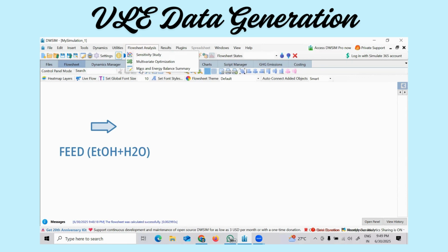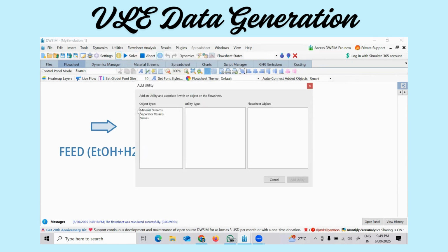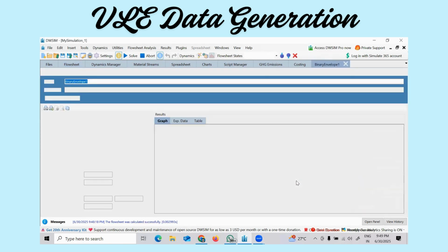Utilities, and then I say add utility, and then material streams. I take binary phase envelope and with stream, and then you can see again, it's all enabled now. Blue colored one, object type is what? Material streams, and utility type binary phase envelope, and then flowsheet object feed, right? Under which stream it already has conditions, right?